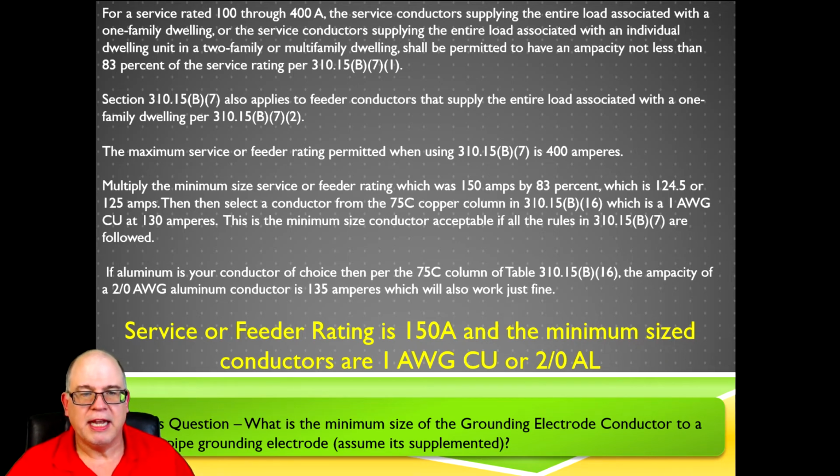All right, so in our case, we're looking at a service. We're going to be rated 100 through 400 amperes, and our calculation was, remember, 150. So it falls in here. Other thing to remember is, in order to use this table or to use this calculation, those service conductors have to handle 100% of the load, folks. 100%. What do we mean?